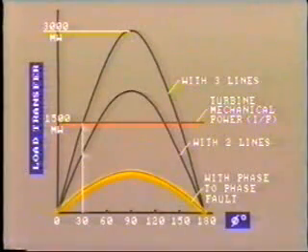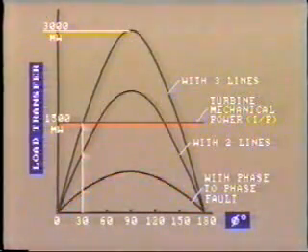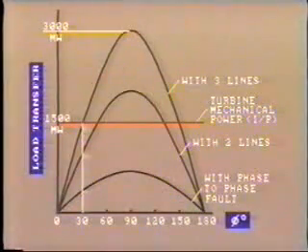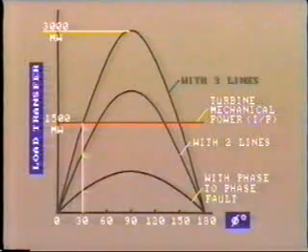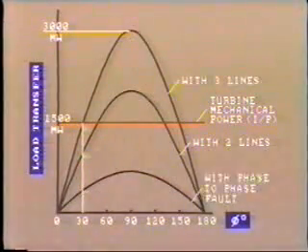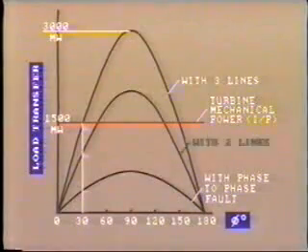Clearly, with these low voltages for any specific angle, the amount of power that can be transferred is now greatly reduced. We now have to consider three power angle curves. They are: 1, the initial condition with 3 lines in service; 2, the condition with the phase-to-phase fault on; and 3, the condition with only 2 lines in service after the faulty line has tripped.